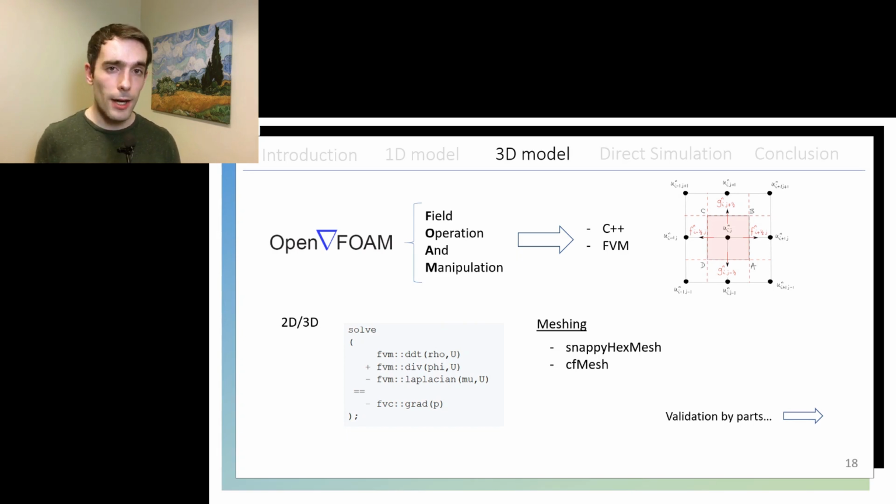It's a method that is similar to the finite element one, only that the solution is stored at the center of the cells. So when computing the flux between two neighboring cells, there is only a single value, which makes the whole method implicitly conservative.